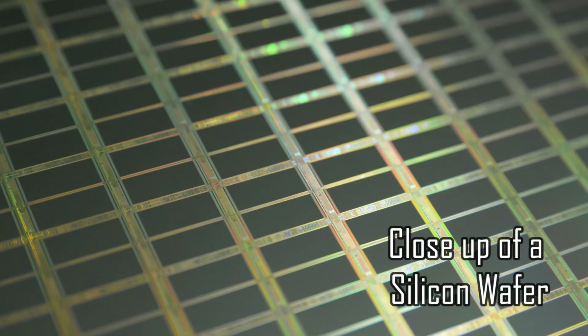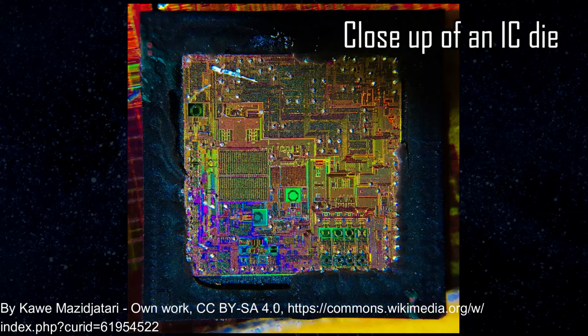A wafer is a piece of silicon or some other semiconductive material in the form of a very thin disk. They serve as a substrate for integrated circuits. Each component on an IC is tiny, usually even microscopic, and are intricately weaved together along with a complex layering of wafers and copper. The wafer is cut or diced into many pieces, each containing a copy of the circuit. Each individual piece is called a die.